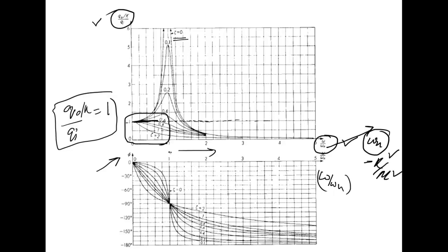So as we desire, we would like to have it between 0 to 1, and between 0 to 1 we would like to even put this into the range where there is a flat curve between the phase angle and the omega by omega n ratio, which is this one, and this corresponds to zeta equal to 0.6 to 0.8.